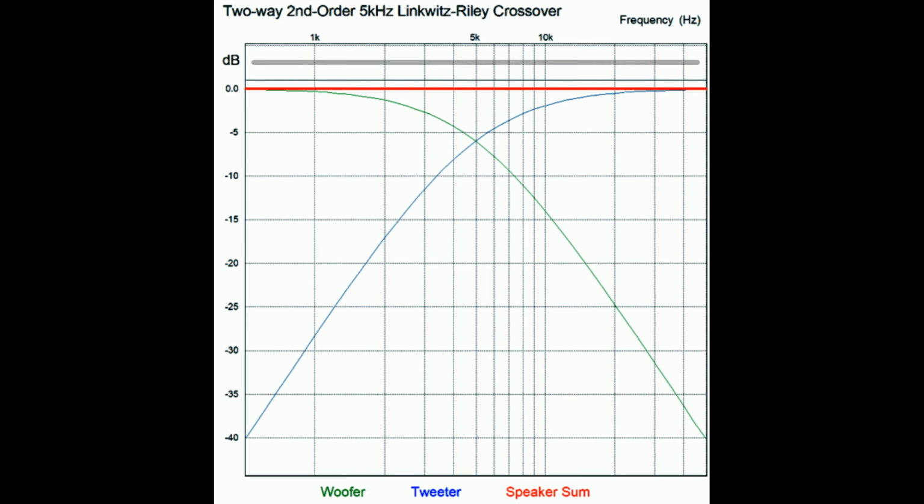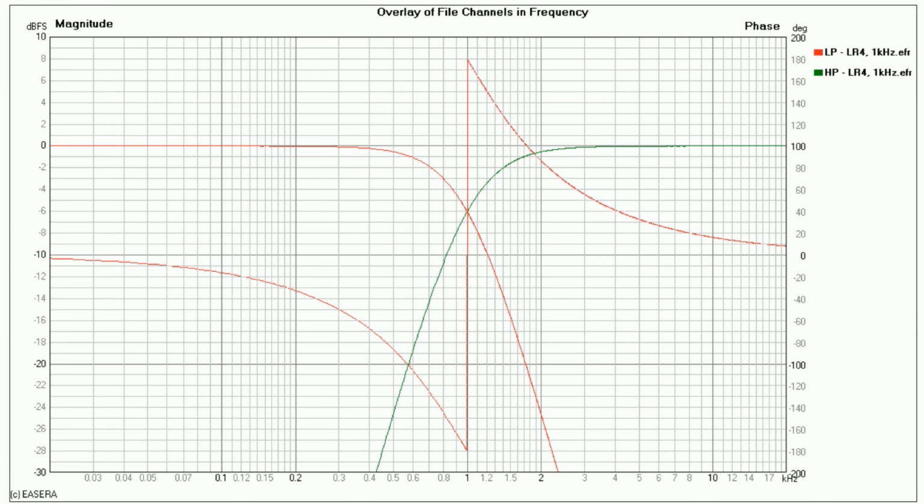The combination of a low-pass and high-pass crossover at the crossover frequency applied to LF and HF drivers respectively will give a reasonably flat overall frequency response. However, crossover effect is not limited to only the frequency response. A crossover network will also cause phase shifts proportional to the order of the filters due to the energy-storing nature of the capacitors. Each capacitor in a circuit contributes a total of 90 degrees of phase shift, which is audible as a time delay between frequencies before and after the crossover frequency.